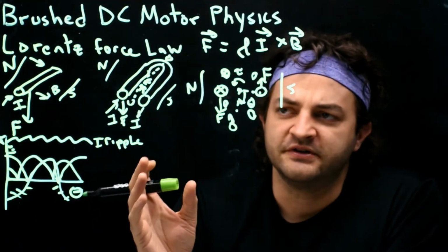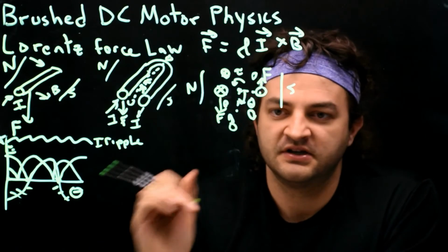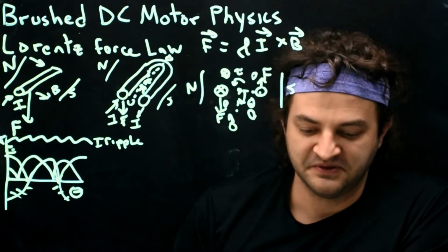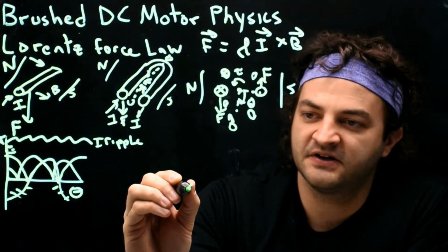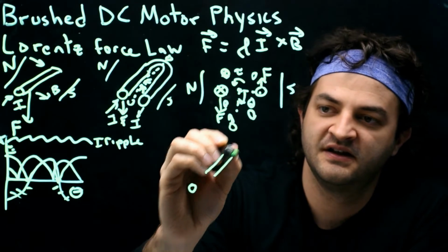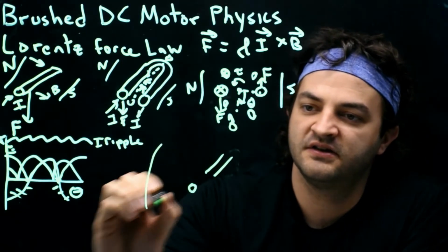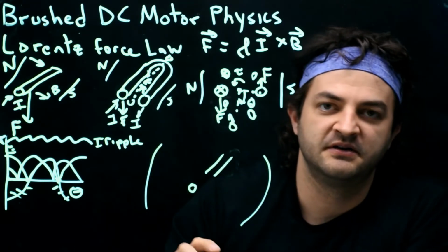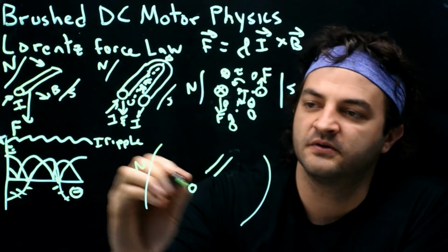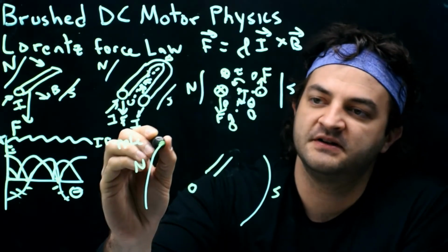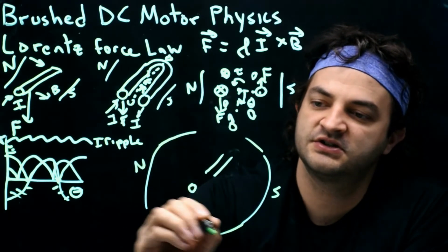So how do we do this mechanical commutation? I'm going to try to draw a picture here. It's not going to turn out well, but we'll see how it goes. So we have the shaft of the motor, and it goes off in this direction. And around the motor, around the housing, is a big semicircular permanent magnet, one with a north face and one with a south face, so that we're still getting our magnetic field. But this would be circular, and they would almost touch at the ends.